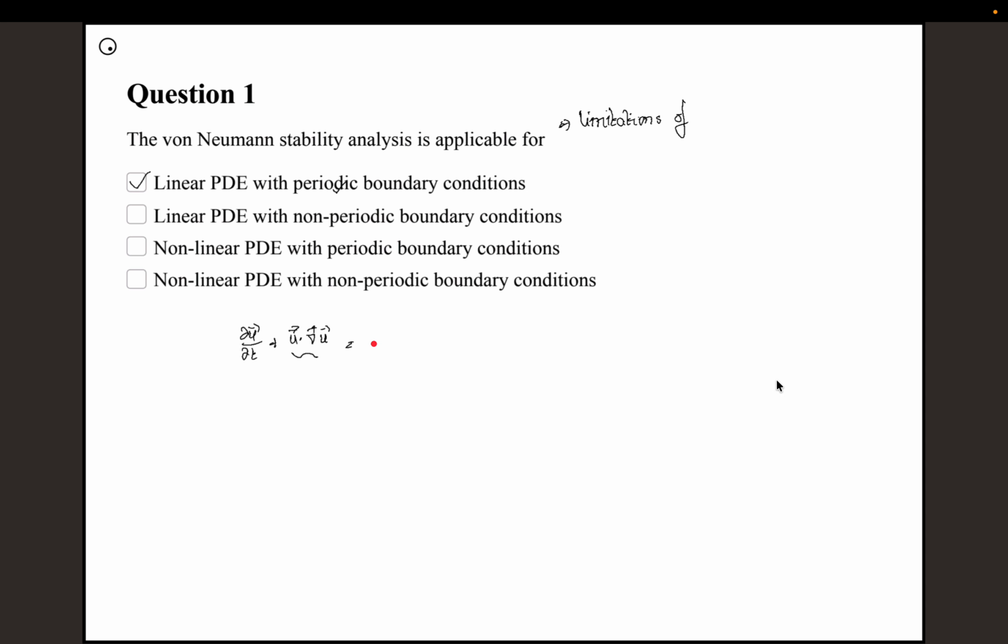You also have in the Navier-Stokes equation the Laplacian term, and let's say the other terms, pressure term and gravity term. But you can see that it has a time derivative, it has this advection component. If the advection is negligible, this is similar to our parabolic equation. If advection is dominant, it's like hyperbolic and so on.